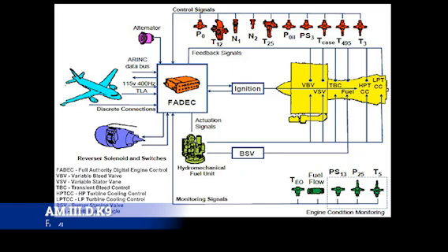Whenever you were running the OH-58 back in the day, you had to motor up to a certain degree, hit the starter, induce fuel, and then keep it going. And you had to watch your EGT, make sure you didn't hung start, and you also don't want to hot start the engine. Whereas with FADEC, once you got it up to a certain NG, you flipped a switch, and it just kind of took care of the rest for you for the most part. You just had to roll up the throttle to over 90% torque, and you were good.